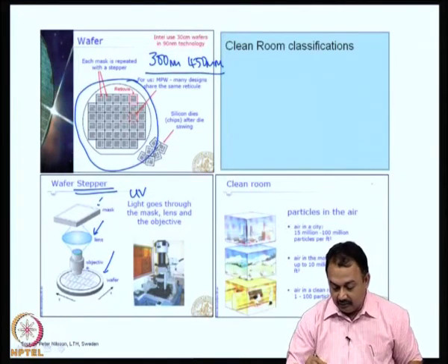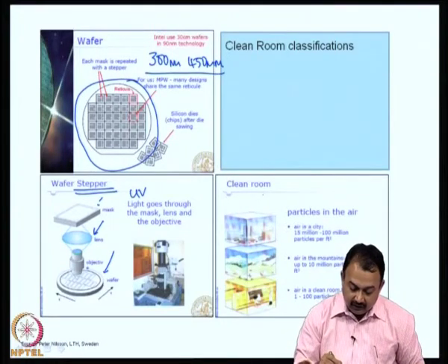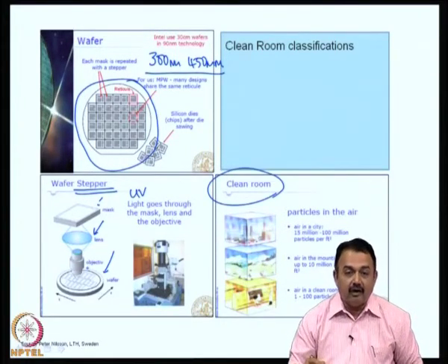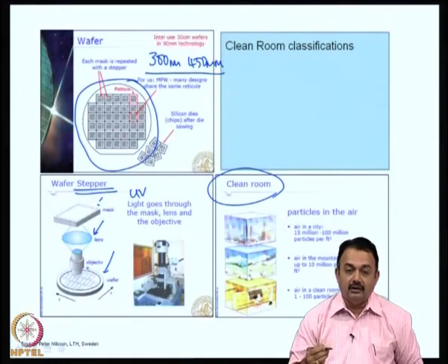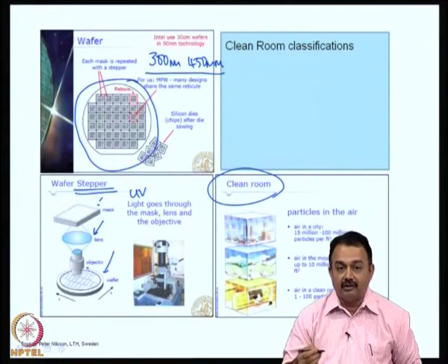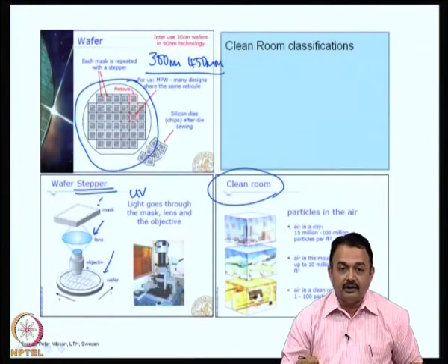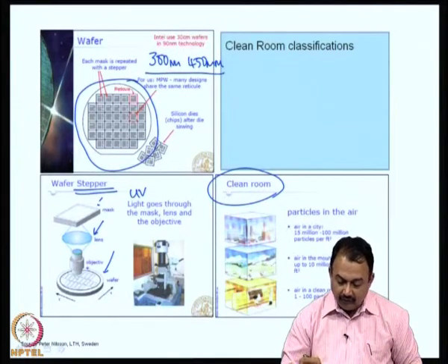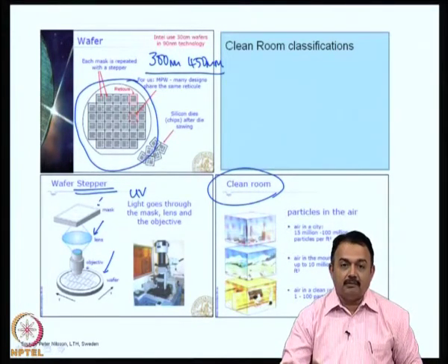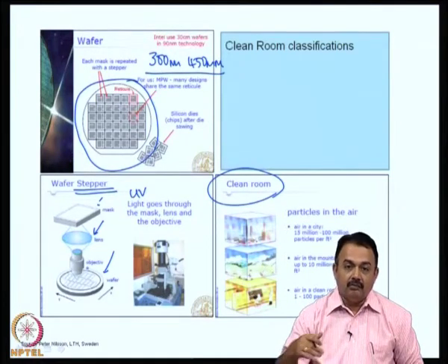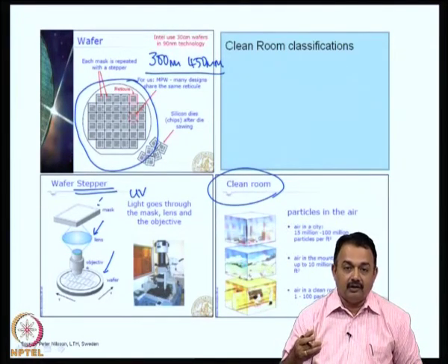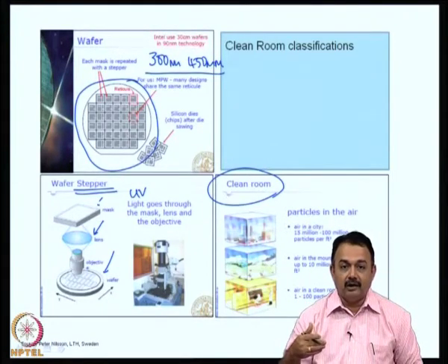Now, any semiconductor manufacturing, it need not be emphasized that you have to give a lot of attention to clean room utility, and you have to monitor the level of cleanliness in the clean room regularly, every half hour. So, there are certain standards to maintain the clean room conditions in large industry. Now, why are we worried about clean room? Because there are dust particles in the air. If a person is entering the lab or the factory, he carries with him a lot of dust from the hair, from the clothes, footwear and so on.